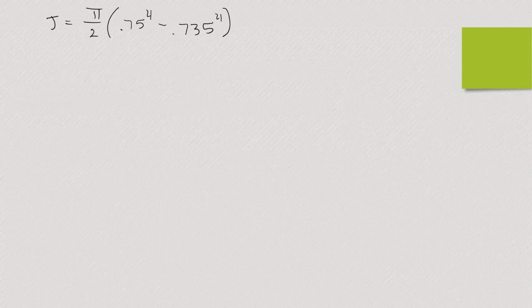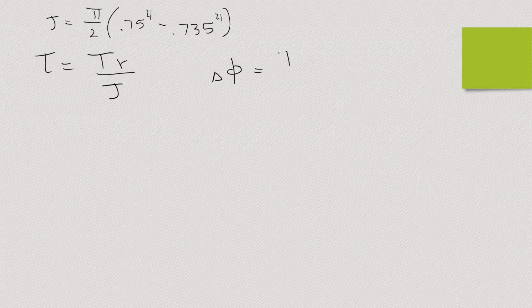Okay, so you're saying that the shear stress equals TR over J? What's that? J times G, right? That's not this equation. There is an equation with JG. What equation is that? Yes, the angle of rotation. So delta theta equals TL over JG, perfect.